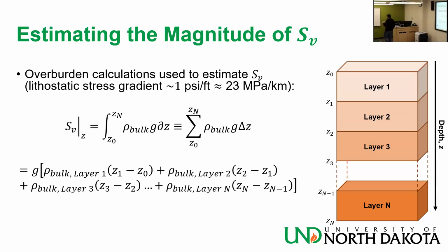It's like assuming that 1 pound mass exerts 32.2 pound force, which is not true. The American units are automatically converted from mass to force. You don't need to multiply by anything. So if you are using American units, just take the G out of the equation. Pretend that it doesn't exist.